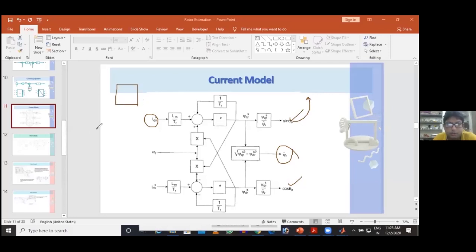I'll show you the model also. From the 3-axis current, it is converting; this omega r is coming from the encoder, and these are the passive parameters. And this is the simple differential equation. This star means integration. It is very, very simple. Here these 3 terms are added, and basically this is equal to d psi rq by dt.